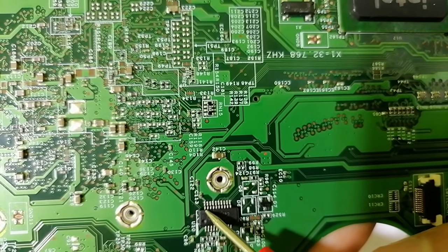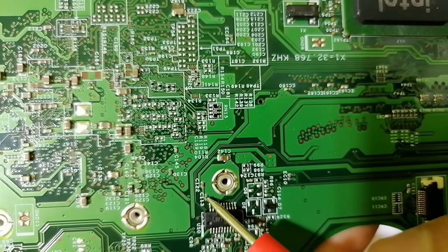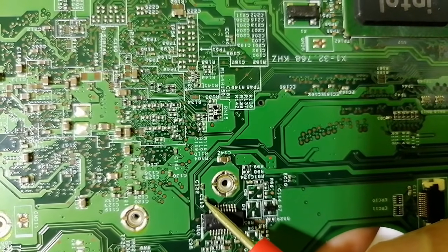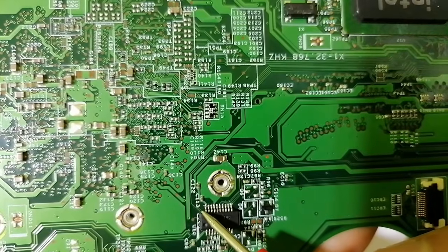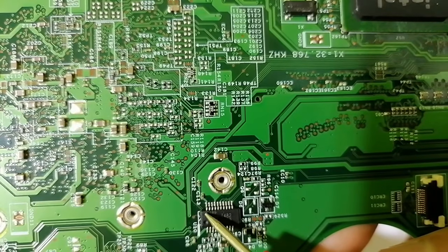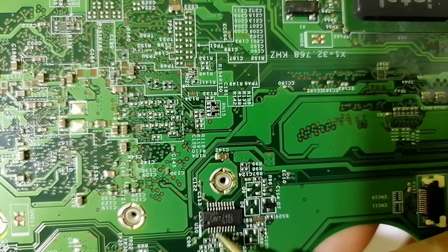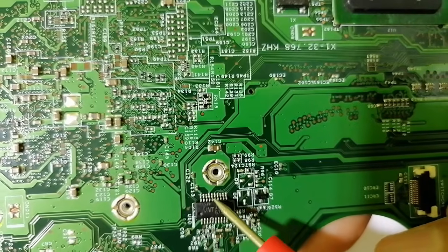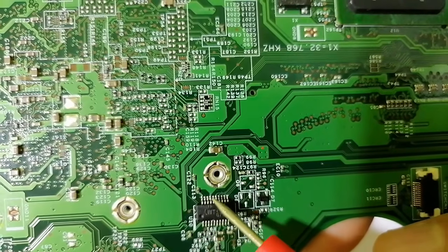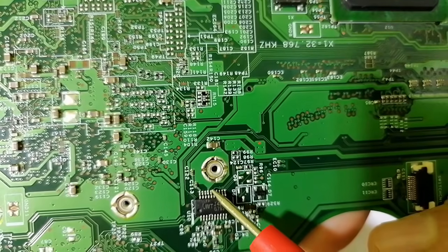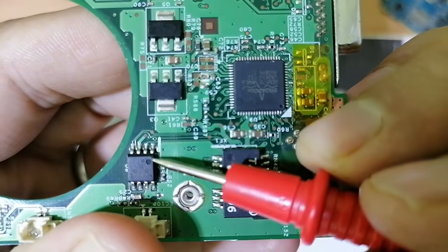So as you can see, the power pin is connected to a ceramic capacitor in order to be filtered. So always the power pin is connected to the ceramic capacitor. Do you see, guys? I can know about all pins without the schematic. So here I have another example.